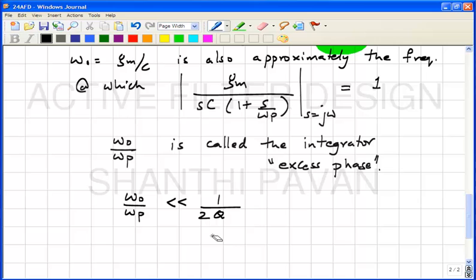Once you have a basic building block, an integrator where the input and output dimensions are the same, you can put integrators in various configurations and realize arbitrary transfer functions. In every case, the steps are the same. You know the transfer function, you come up with a network, then you dynamic range scale the network, which will maximize dynamic range, and you're done. So the building block is an integrator. Whenever you're designing a filter, the first thing you will do is design an integrator and see how good or bad it is.